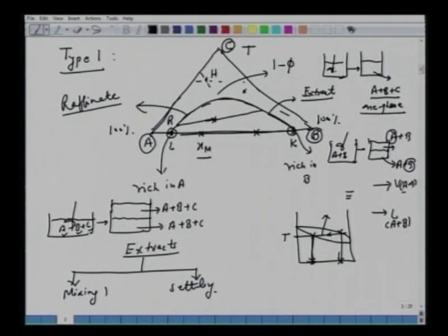So you represent it like a CSTR reactor, and here you have a very simple settler, no mixing. So we have taken this, we have mixed them, A plus B plus C, temperature is fixed, allow them to settle, we get 2 phases, raffinate and extract. Raffinate phase contains a certain amount of C, which is smaller than what we have in the extract. That's what we would expect.